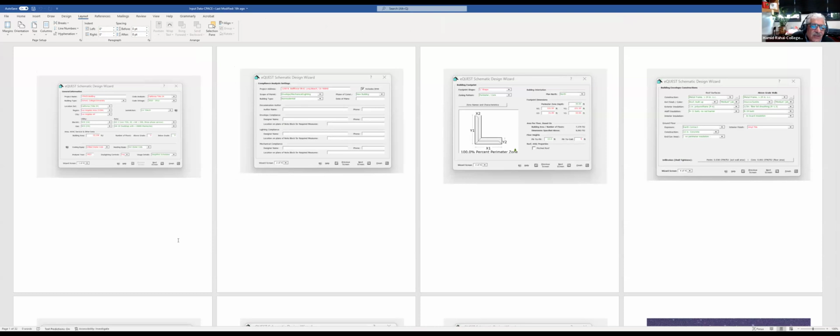But once you start eQuest, you get this kind of window that you need to specify. So you identify the type of building, the title of the building, the climate, the location site, and which utility company is used automatically comes up, and so on. And then the address, and then the shape of the building. Either they have options to import this, or actually click and select from the type.